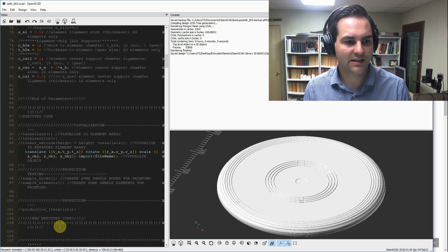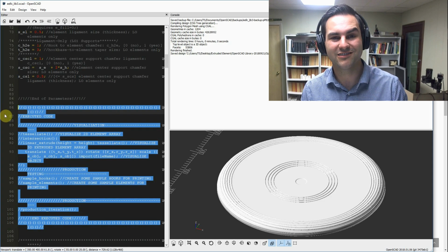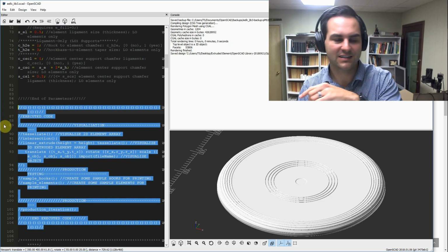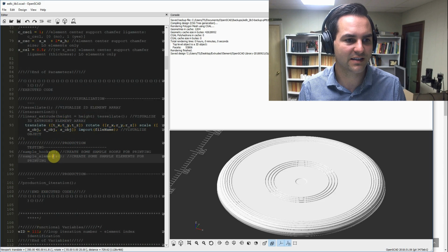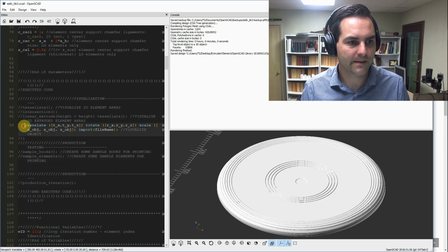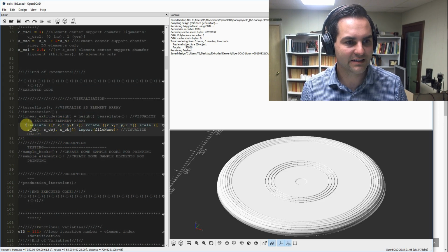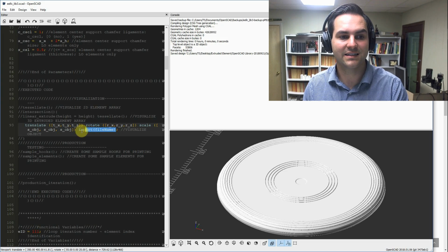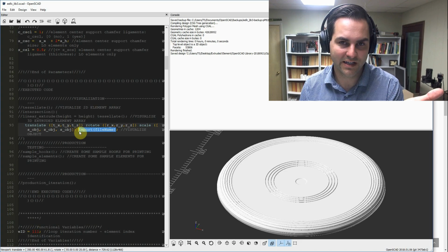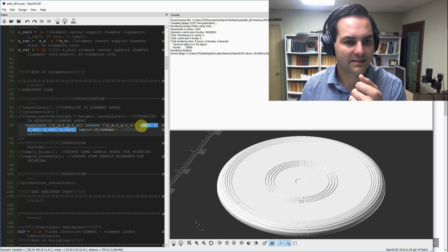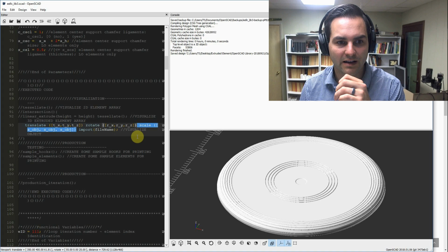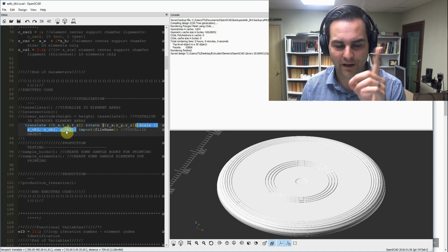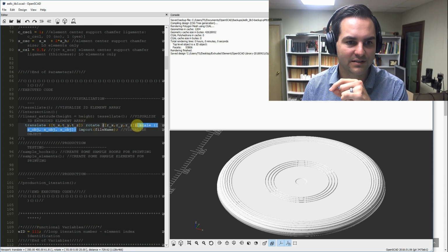You then go down to the executed code where you'll be doing a lot of, again, commenting with backslashes, uncommenting, removing those backslashes. And you uncomment this line right here, which is visualize object. It starts with translate, ends with import file name. Meaning this line is importing file name, which is frisbee.stl. It is then scaling that imported object by whatever scaling factor you given those options up top.